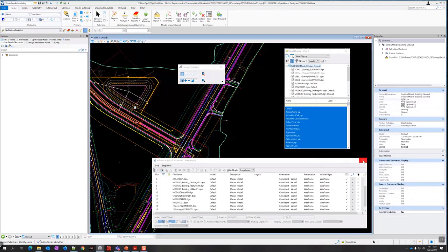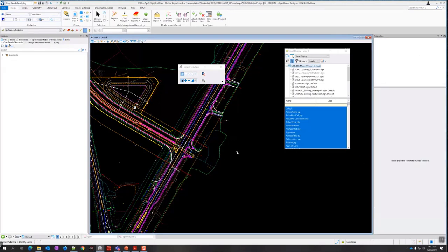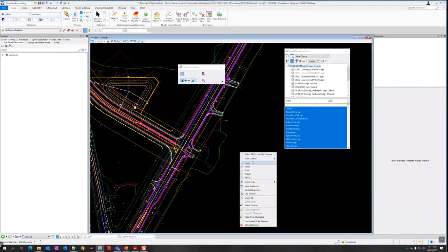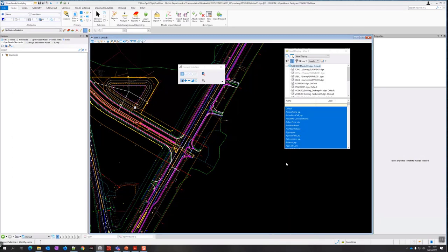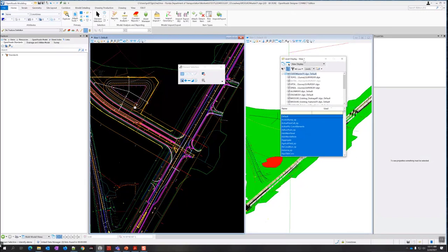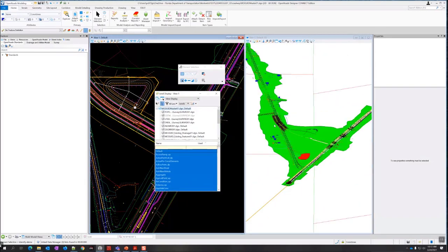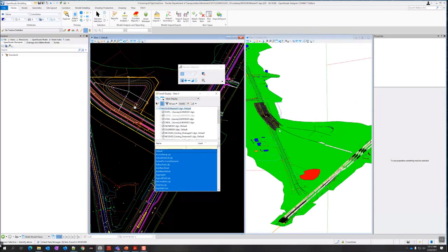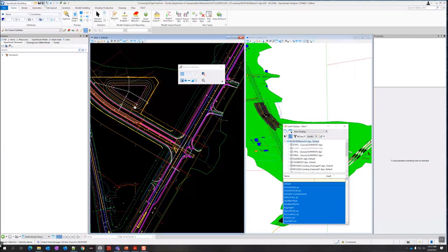And I should make sure also that we have a 3D view created so that I can use the F2 key or the view control here and then do plan in 3D. Just to make sure we got 3D information. So it looks like we do. It's there. I'm going to go ahead and save settings. All right, so that's my master model.